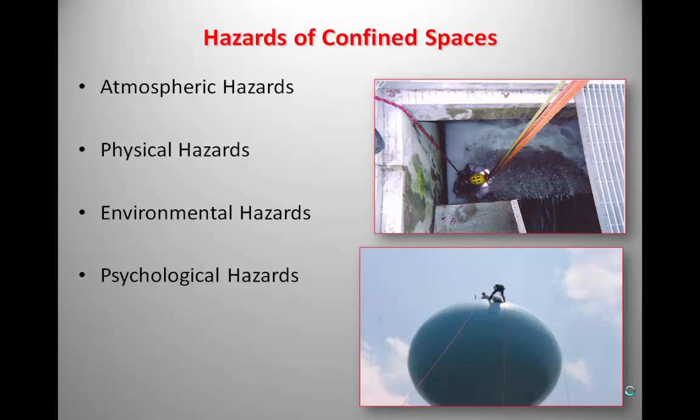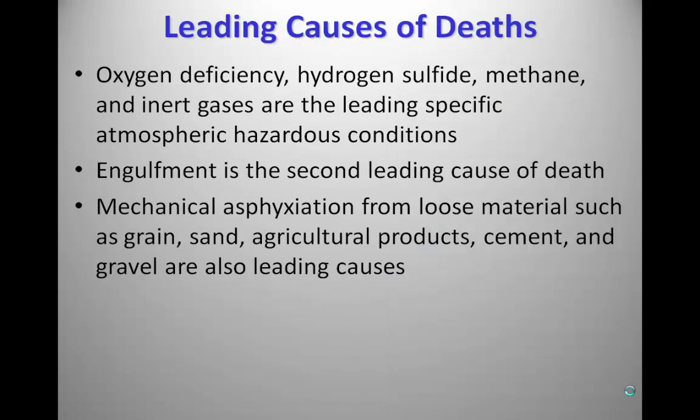The leading cause of death is oxygen deficiency, hydrogen sulfide, methane, inert gases, or just to abbreviate it, atmospheric hazards. Atmospheric hazards are the leading cause of deaths in confined spaces, followed by engulfment and then mechanical asphyxiation.